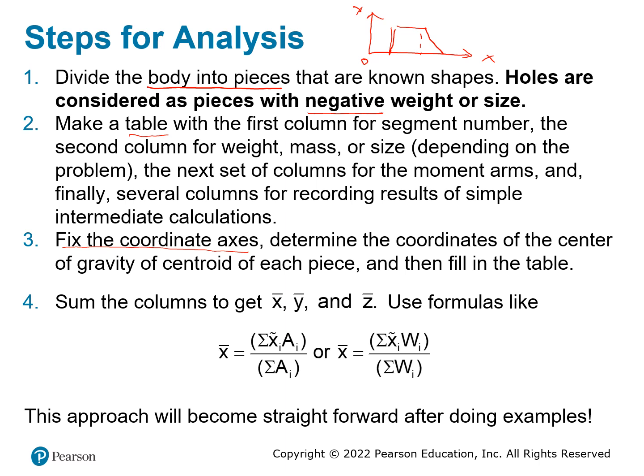You make a coordinate axis by selecting this one as the origin. Then this shape is going to be away from this point, from the center point, about this much. And the second one is the triangle, right? And the triangle has a center of mass which is 1/3 to the base. So the second one also has an x-distance like this.